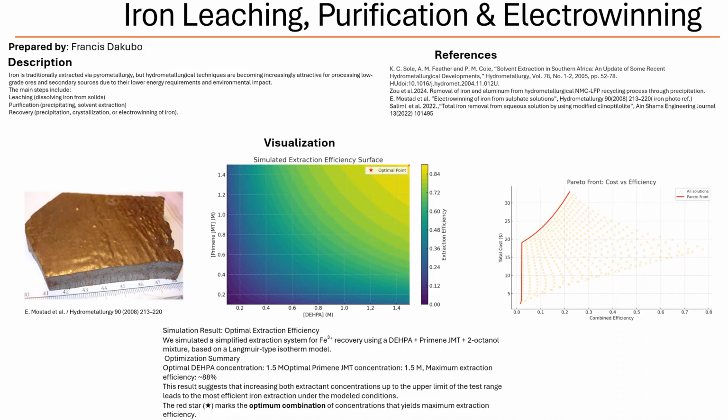iron. What did they do with that ferric iron? It's not ideal for the process, right? They treated it with hydrogen sulfide gas to convert it back to ferrous iron before recycling the anolyte. Smart. So what about the quality of the iron they produced? They were aiming for a ductile iron with a smooth surface, something you could actually use for manufacturing.